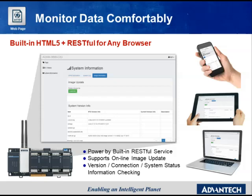The web service function is built on HTML5 with RESTful, works with any browser, and is powered by a built-in RESTful service. Users could use their notebook, pad, or smartphone to see the status of tags on ADAM3600 directly, and they could also modify the value of the tags once they log in to the web service page. Additional features such as online image update and version checking can also be achieved with the online web service page.